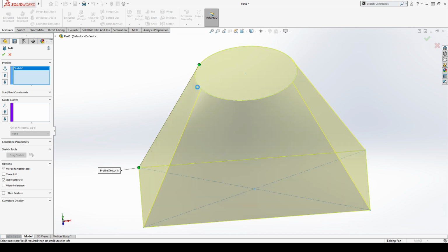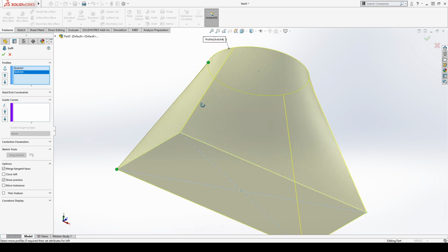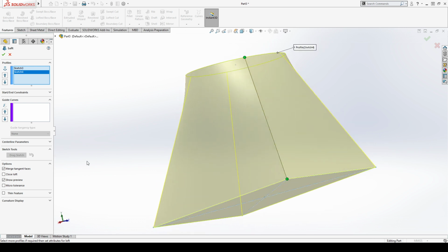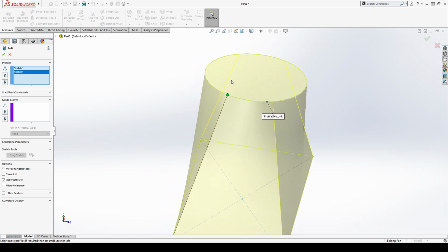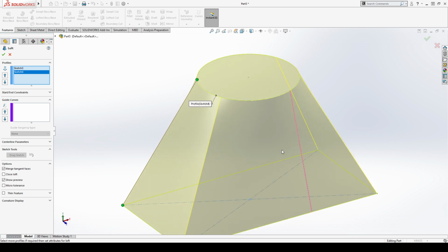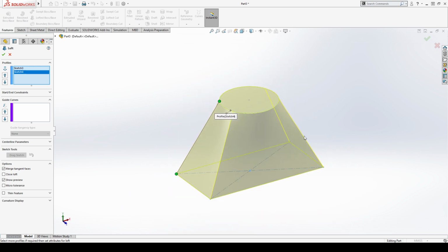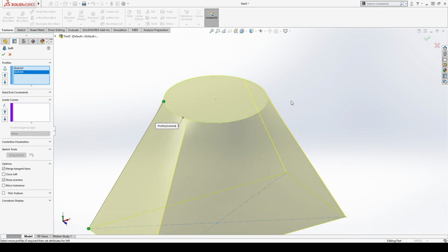Cool. That profile, see, it still works. What SolidWorks does at this point is it basically cuts apart your sketch into segments on its own. So it starts to guess at where you'd want to split it up. In this case, because we have a rectangle here, it's taking the perimeter of the rectangle and normalizing how long this edge is with respect to the perimeter, making that same scale change here with the perimeter of the circle. So this arc length proportional to the circumference of the circle is the same as this line length proportional to the perimeter of that.